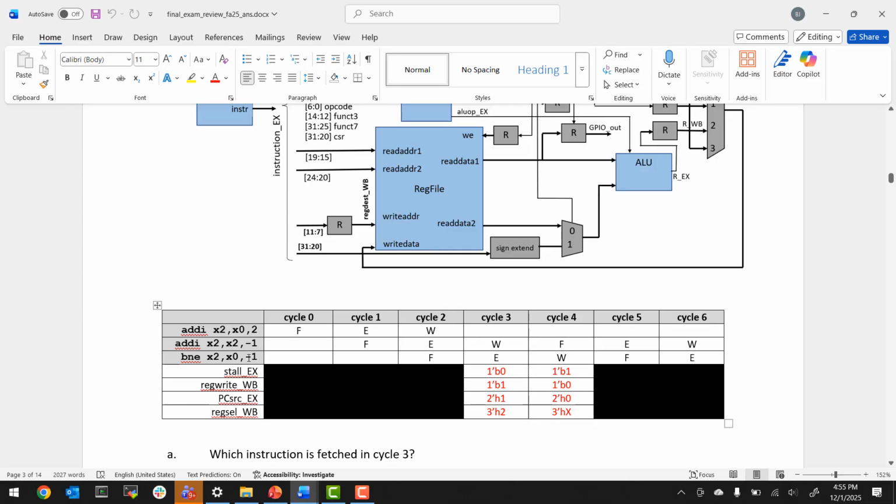And remember, I told you that -1 means go up one instruction, right? If this were MIPS, -1 means branch to yourself. But in RISC-V, -1 means go up 1 because of the way they calculate the branch offsets. Okay, so anyway, the cool thing here is, this always kind of gets me, okay, so when the branch is in execute is where we're going to resolve.